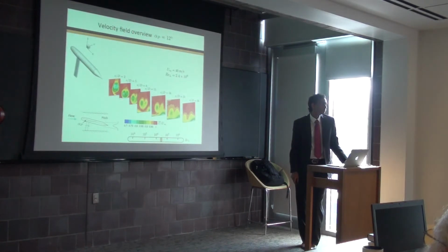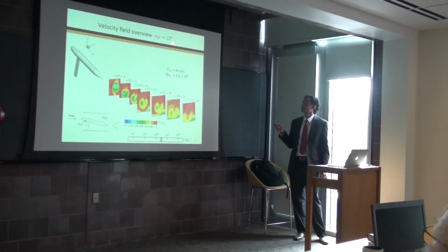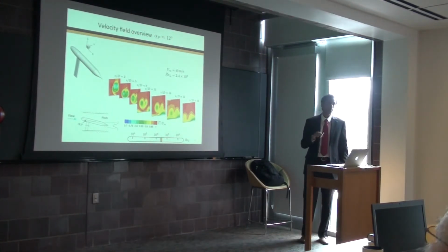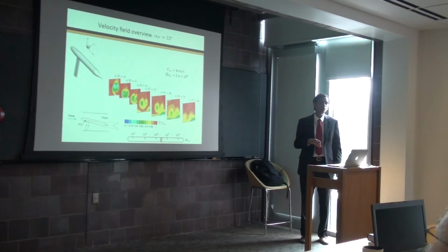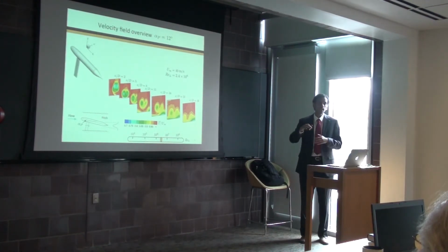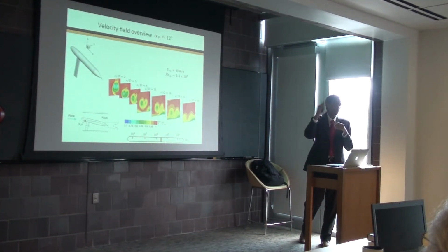You might want to mention the observations on missile aerodynamics. Yeah. So one thing here, of course, is that these were performed at relatively modest angles, as compared to some of the things that I showed in the literature. At very high angles of attack in the 1960s, people were very interested in missile aerodynamics. These are slightly different bodies to the types of bodies we see. They're basically like delta wings. They have sharp noses at very high angles of attack, above 40.